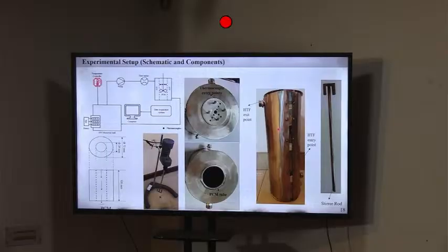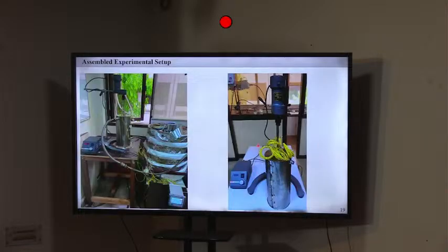We wanted to understand whether the stirring mechanism is actually helping enhance the charging mechanism, because when I am introducing stirring, it is actually power consumption. As I am saying, 100 watt of power is required. Is it worth using 100 watt of power to enhance the overall charging of the thermal battery? That was the main point of this experiment.